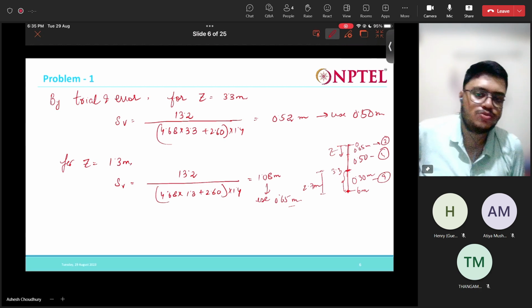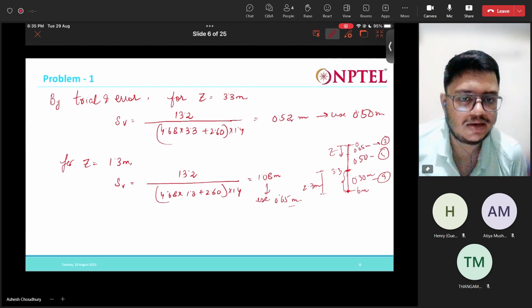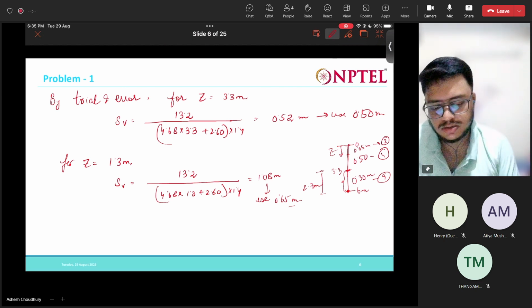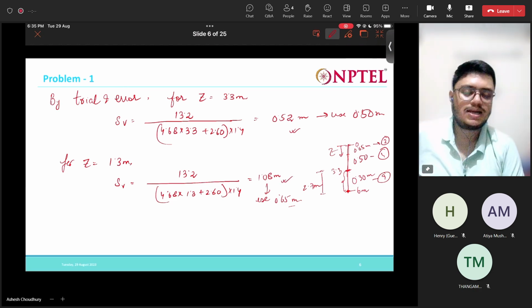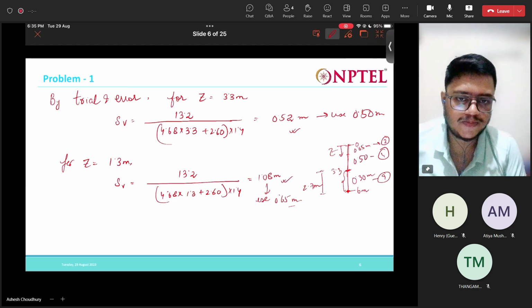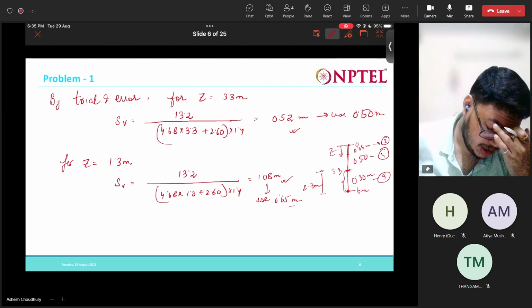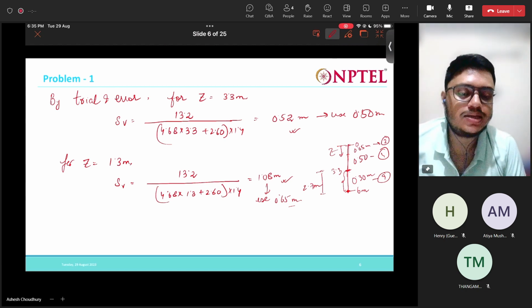It is up to you how to adjust all this reinforcement spacing. You just need to do some trial and error and check and adjust the spacing. So the maximum depth spacing is coming as 0.30 meter. So we decided we will provide 9 layers with that.